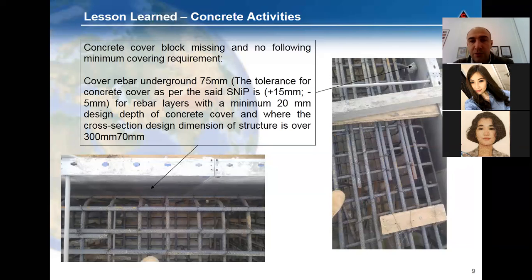So every time you need to look at the thickness of the cover to protect future reinforcement from corrosion. For each construction, the thickness of the protecting concrete cover is not the same, and it's special for each construction. Also, it depends on the thickness of the steel rebar.